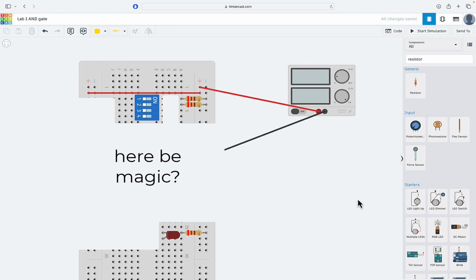I've completed building the circuit. I'm going to hide what I did because, well, that's going to be up to you to figure out. But I will show you how to test that your circuit works in order to determine whether or not you've done this correctly. What we need to do is check that the truth table of this circuit matches the expected truth table for each digital logic chip. In this case, I expect the truth table to be that of an AND gate.